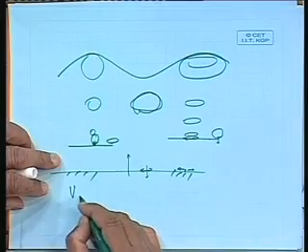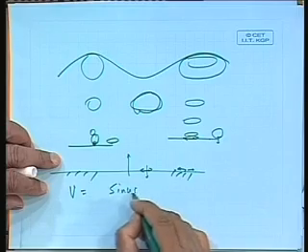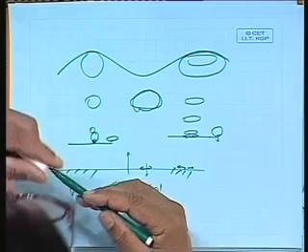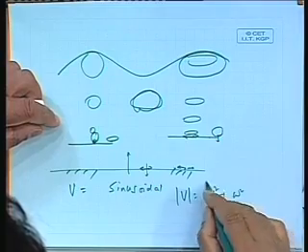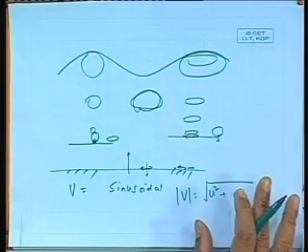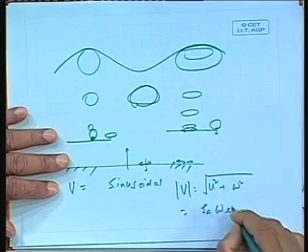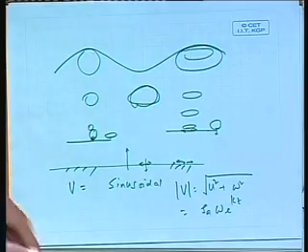Now, this is about the velocity, and you see the velocity becomes important. Therefore, we find that the velocity is sinusoidal. Everything is sinusoidal actually, and interestingly, when u is maximum, w is 0, and when w is maximum, u is 0, and so on. The two components don't have their maximum at the same time. If you take the amplitude as the square root of u squared plus w squared, you will find that this has a constant value. This will turn out to be xi_a times omega, something like that. So, these are all well known facts.